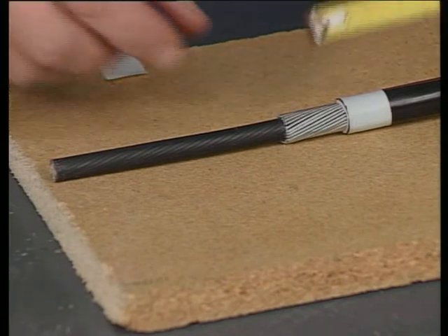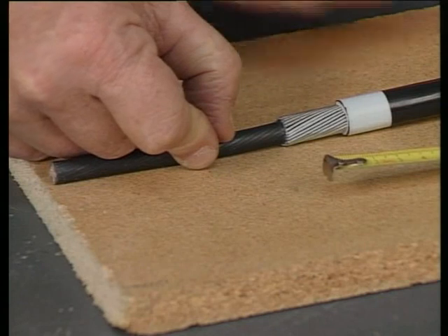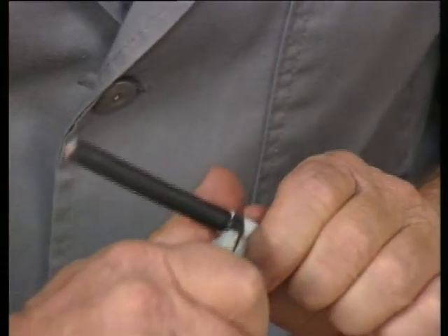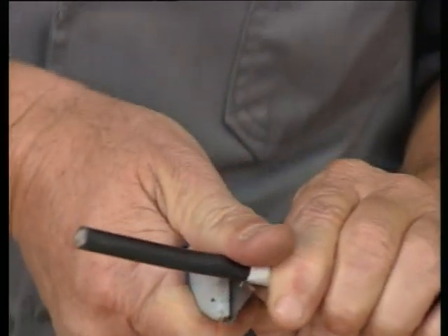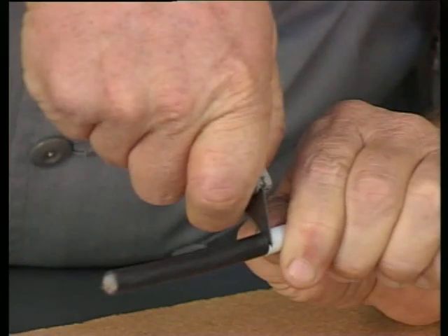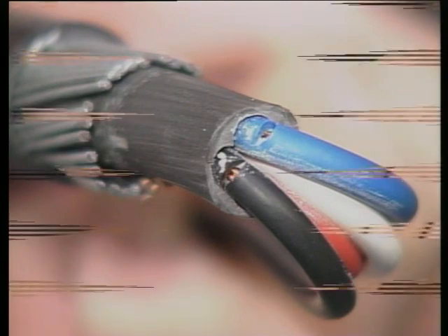Now we have to deal with the bedding layer, which is first measured and marked to the desired or specified length. A sharp knife is again employed to make a ring cut against the marker. You will require practice to develop the feel required to make a cut without penetrating the core insulation below the bedding. Any damage caused by the knife blade to the core insulation creates a potential hazard, and in terms of the regulations, such damage renders the cable unsafe and unfit to use.